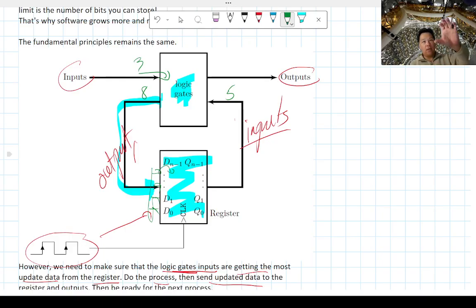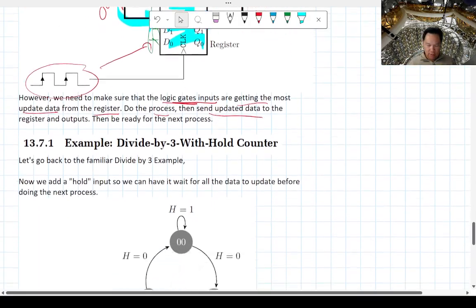Okay, so you have the clock cycle that does your computation. You have one clock cycle to store stuff. Okay, and then you have one more clock cycle in order for you to read it, if you wanted to use it for your next output, and then you have your next clock cycle. So a lot of times what you want to do is actually have these things hold and not do anything. A lot of times, about half the time, your processor and your memory are just waiting for one or the other. Okay, this is kind of the inefficiency of these.